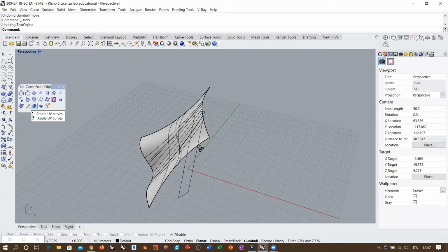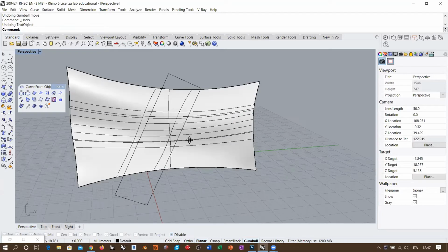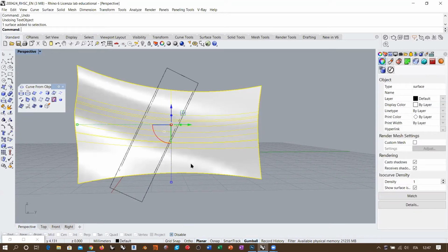We saw that surfaces have geometric dimensions and parametric dimensions. If I should say what's the horizontal and vertical dimension of this surface, I'm in trouble, because one thing is to create a deformable plane which has a domain coincident with the geometry, and then measure it.